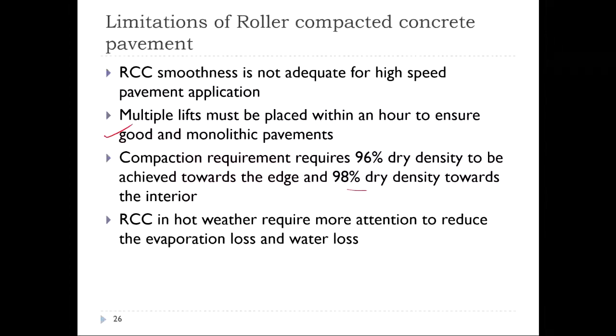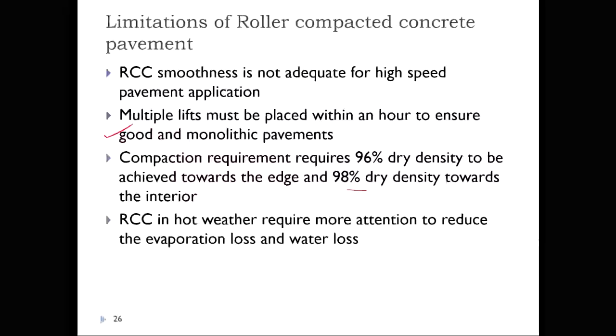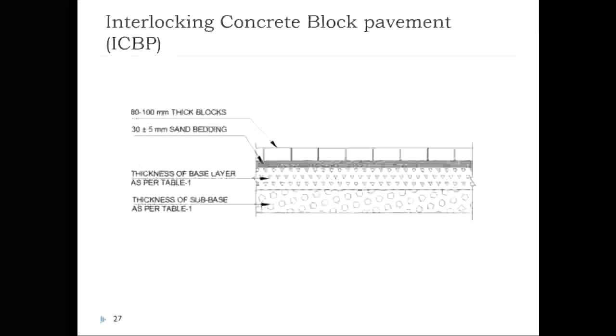Now, in the case of hot weather, you are more likely to have more loss in moisture. First of all, our moisture content in RCC is lesser when compared to conventional concrete. So this is of concern in the case of hot weather paving, because this can drastically affect your workability.